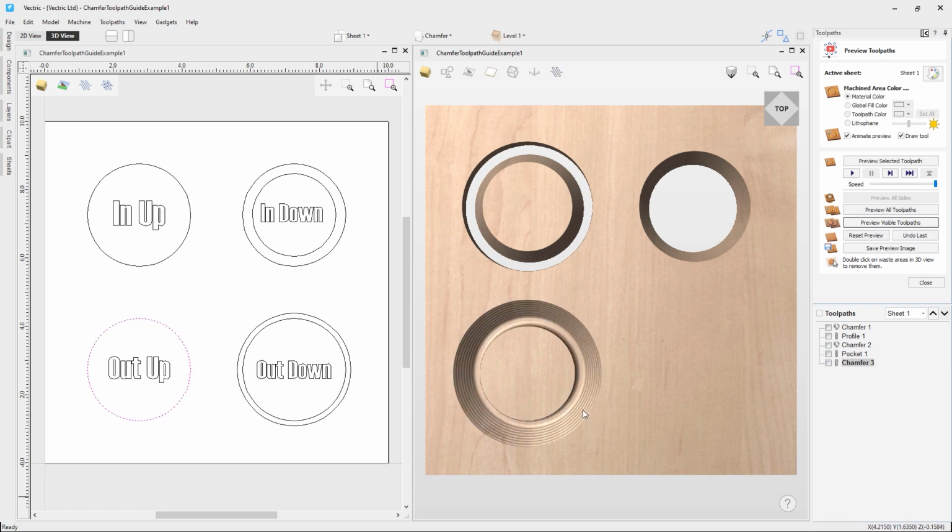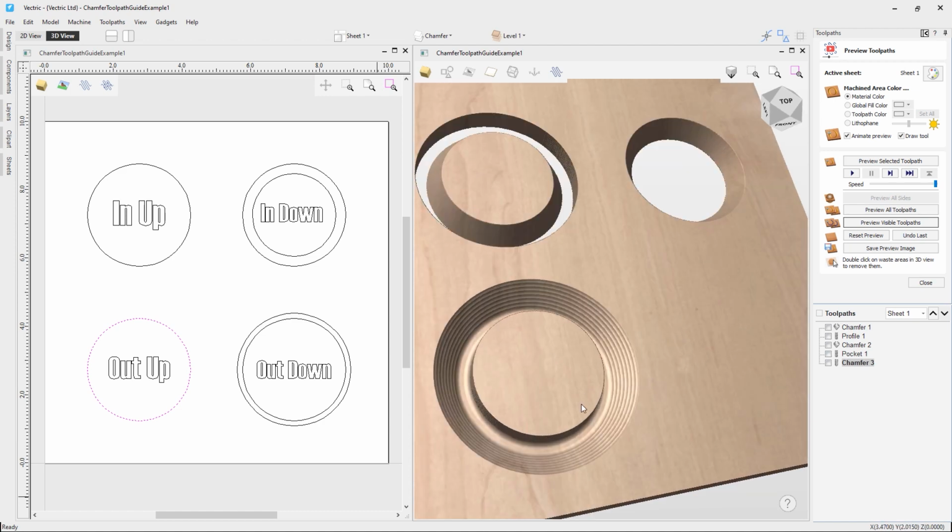And now let's right mouse click, and let's zoom in a little bit just to have a look at this current toolpath. So as it stands, this isn't exactly smooth, and this comes down to the pass depth of the tool itself. So if we decrease the pass depth, that'll create smaller steps, and the results will be much smoother. So what we can do is close this down.